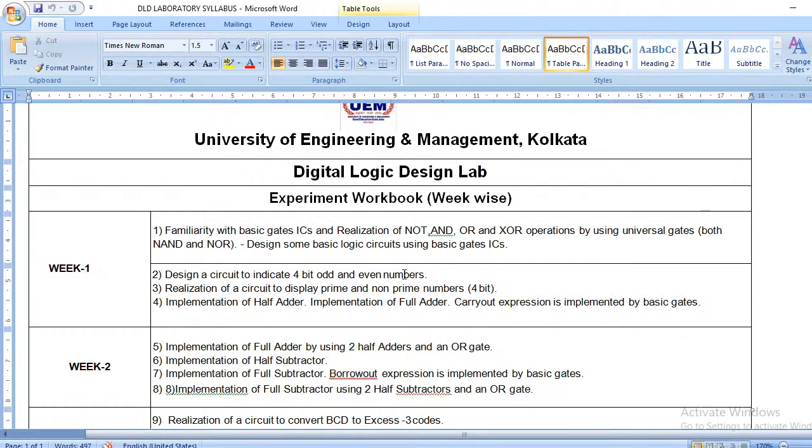to do is understand what the input variables are and what the output variables are, and from the input and output, from the first year you know how to draw the truth table, right? Or how to calculate the truth table out of that. So first of all, you have to know the inputs, the outputs, and how to make the truth table, okay? So first thing is input, second is output, third is the truth table, fourth is from the truth table we will get the equation or the functions.